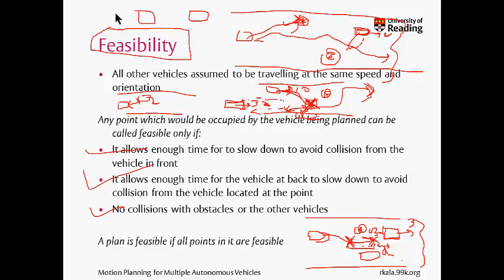So I'll check that in my planning scenario, in any scenario, I should have enough time to stop, sufficiently catering to the needs of this vehicle. So if there is a slow moving vehicle here and I'm a fast moving vehicle, and this is the scenario somewhere in the future, I should have enough time to stop considering distance d1, and the vehicle behind me, suppose it's traveling at a higher speed than me, should have enough time to stop as per distance d2. These are the two additional constraints, because I'm making partial plans, not complete plans.